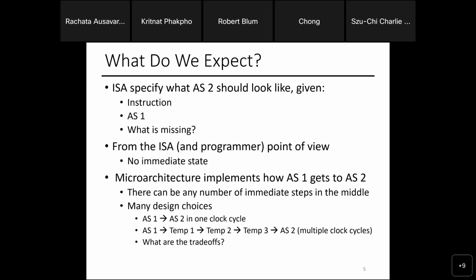Now, let's say I have some magic that says I can clock it fast. Then in the middle, once I clock, I save my progress. So I just clock it based on the fastest instruction. The fastest instruction finishes in 1 clock, but let's say I have to do a multiply, I just need 3 clock cycles. Would that be okay? If I can save my progress when I do the multiply, it's okay, right? It's totally okay. So in that case, I can clock faster. What's the benefit then?